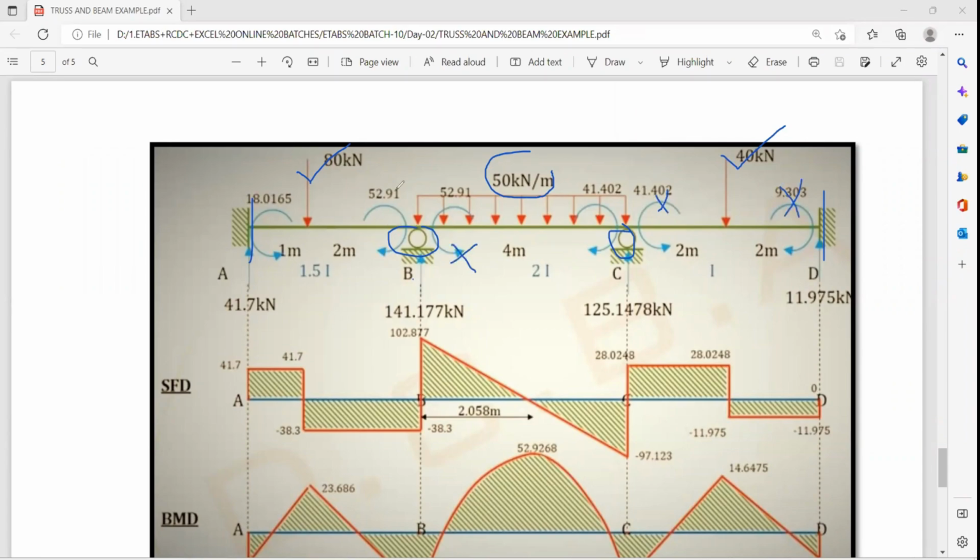These are the results. You might have studied the moment distribution method in your academics. So this problem has been solved by that moment distribution method. So in the moment distribution method, what are we doing? We are using the carryover factor for transferring of the moment, and we are rounding off the moment, and finally we are getting the result, rounded results. That is an approximate result, not the exact result we can call that answer. So this problem was solved by the moment distribution method, MDM.